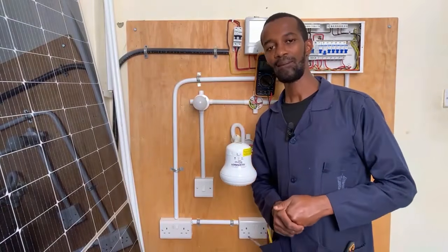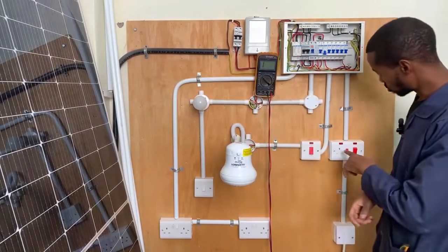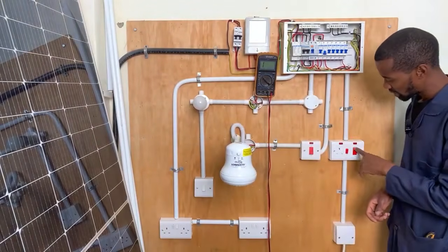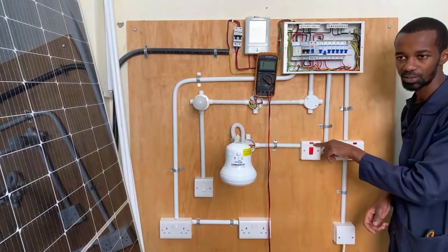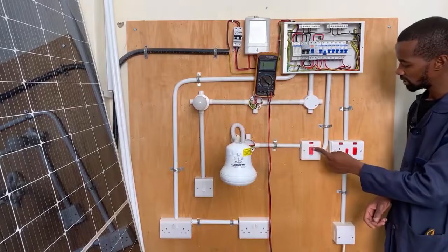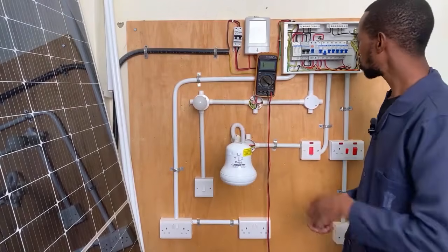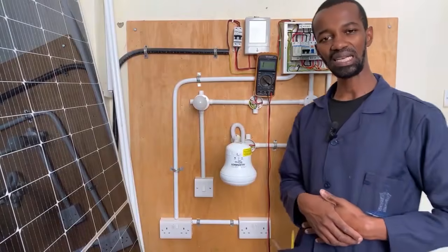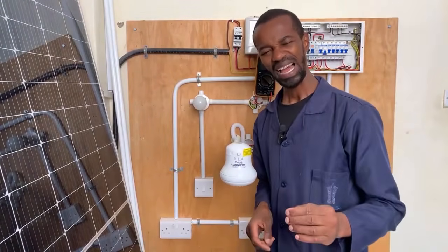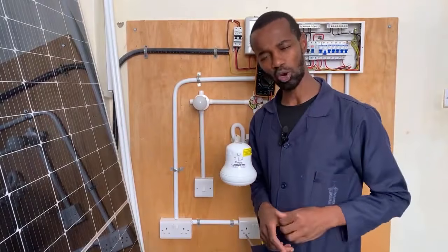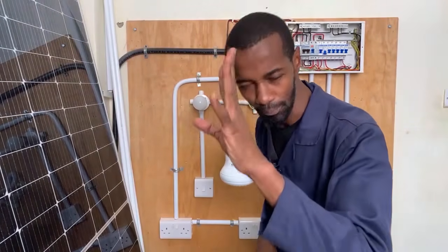But if they say the cooker unit, this one, is not powering on, as you can see, is the shower head powering on? You put on that and it is powering on, then it means that there's a problem with that circuit. You go to the consumer unit as the electrician, you find that there is a breaker that has tripped. You do not lift that breaker or power it on before you find where the fault is. Isolate the cooker.